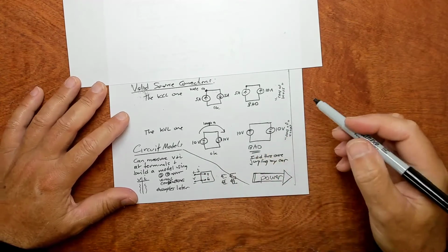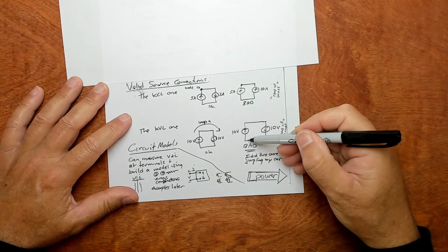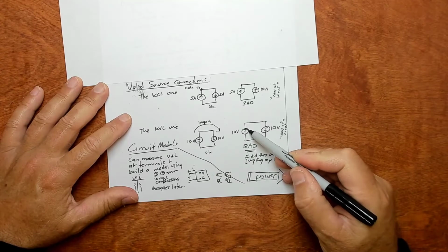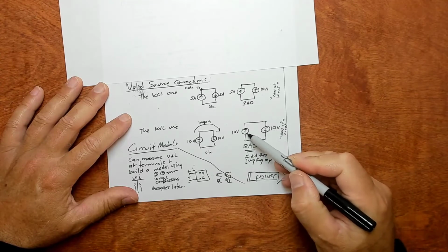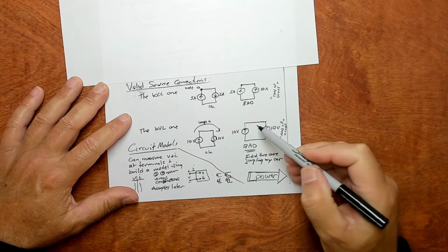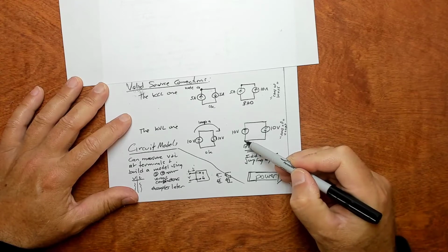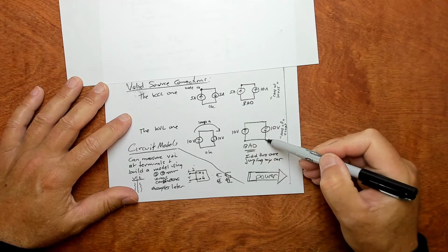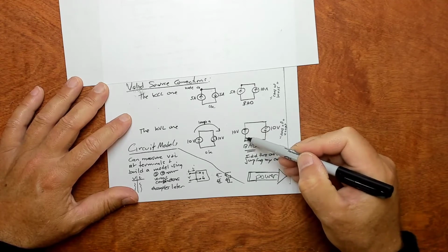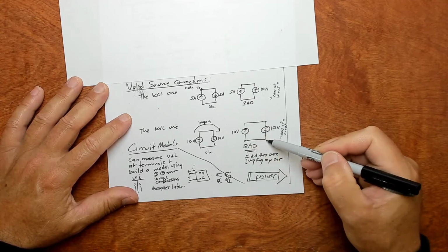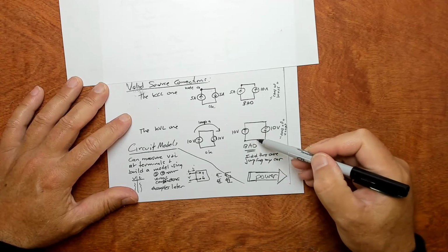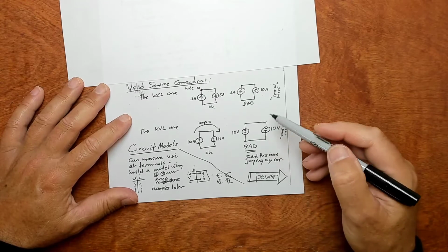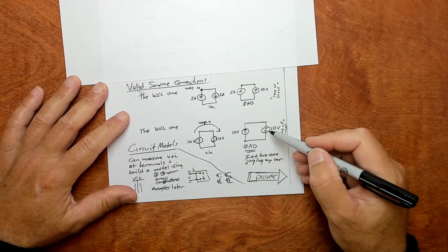And these guys can coexist. But here, if you hook them up like this, positive to negative and negative to positive, this is bad. Here, if you start out at 0 volts down here, this guy's going to raise it 10 volts, and coming over here, this guy's going to raise it another 10 volts. Come back over here, it's going to raise it another 10 volts, and another 10 volts, and it's just going to go around to infinity until you have infinite voltage, which is not a good situation.